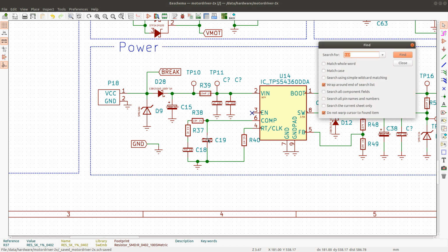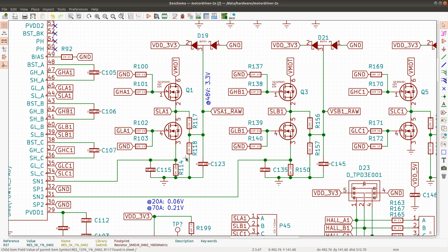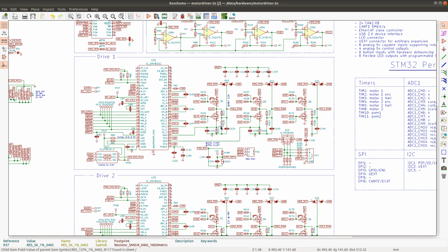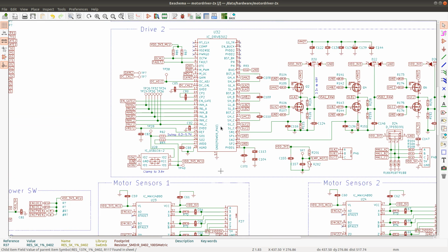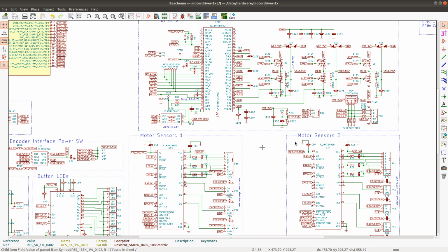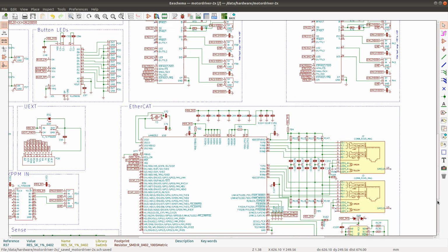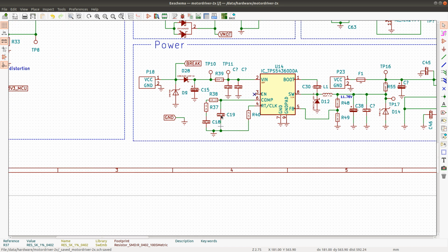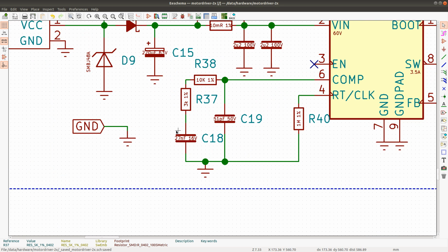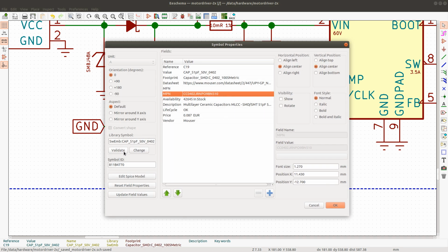I don't think I have anything that's 200 picofarads, or in any sort of picofarad range for that matter. So I think I'll have to just find a capacitor that's 200 picofarads. And I'll keep this one at 27 nanofarads because that's close enough. But let's see what we can replace this one with.